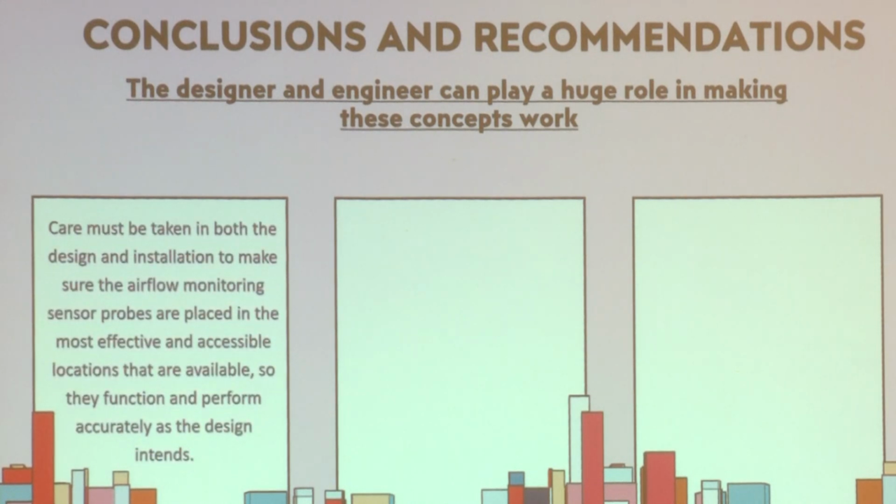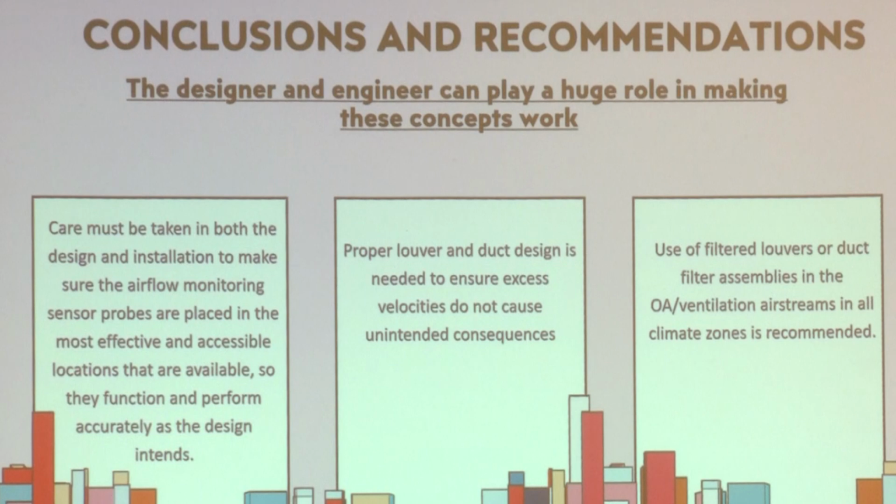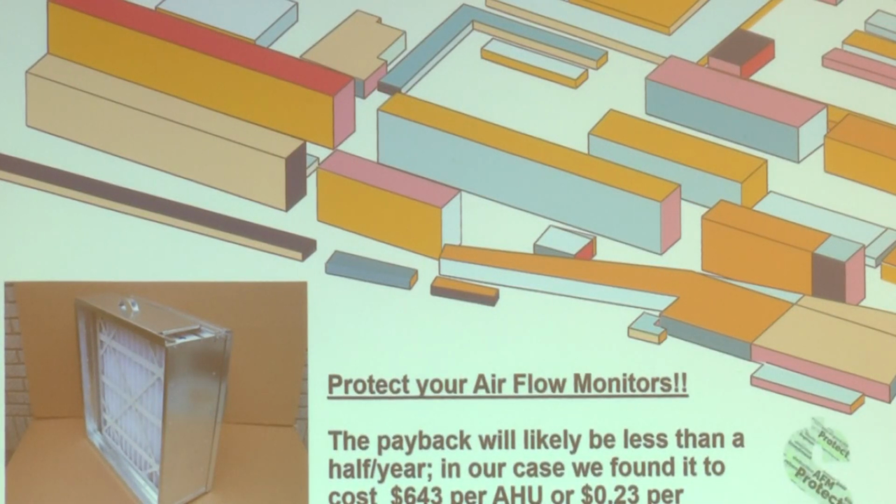All they have to do is take good, reasonable care in the design and installation to make sure that, A, the airflow monitor sensor probes are located in the correct position, but also that they are filtered. They need to make sure that the louvers and the duct designs are correct, and make sure that they bring these filtered louvers, these duct filter assemblies, into the construction, and that they're done. It's simple. Just do it and we'll solve the problem. It's really not a big deal.